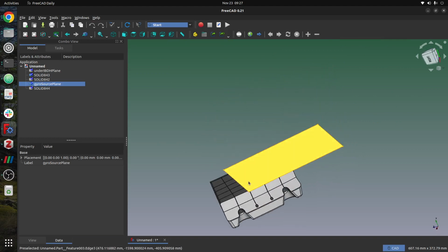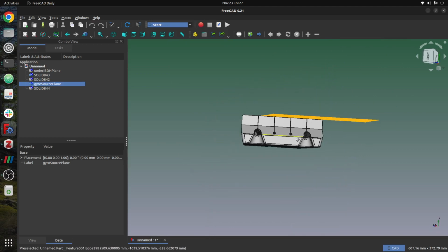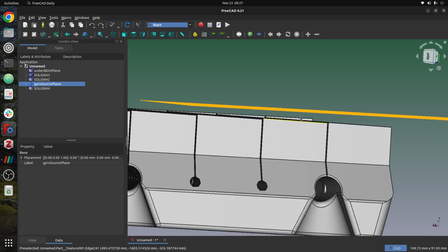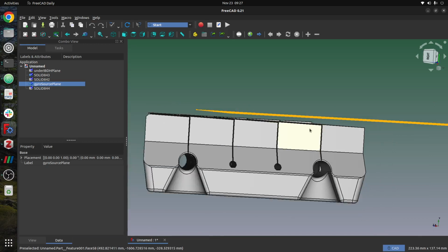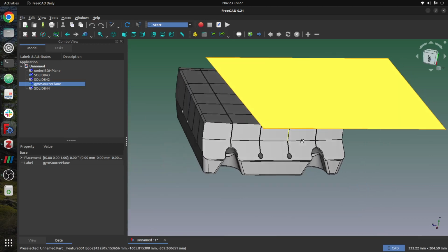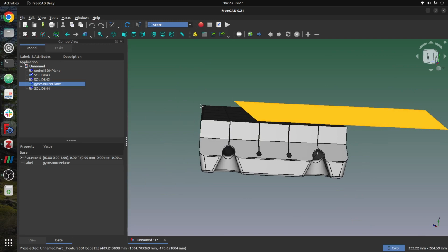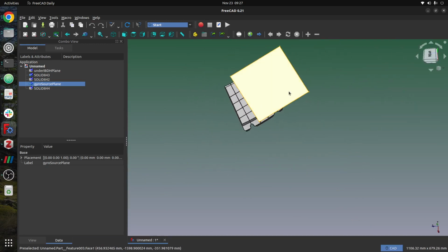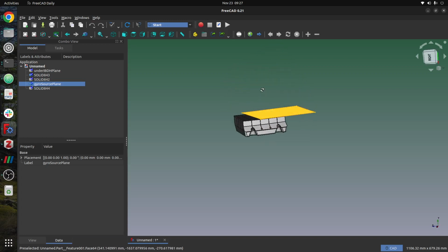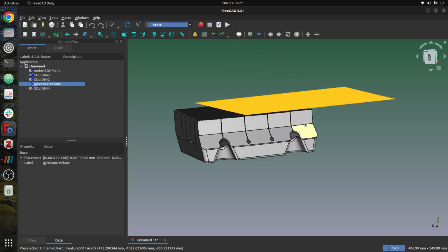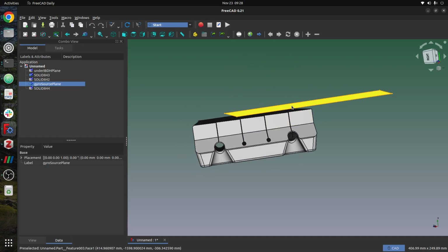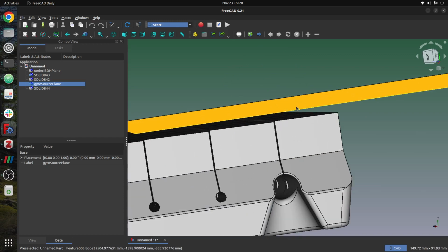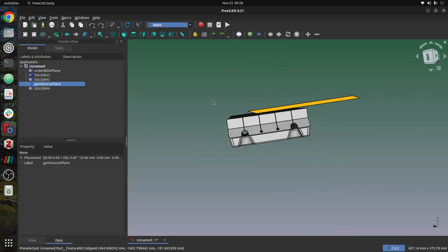Because the field lines in this particular magnetic configuration are coming from right to left and going down, I've also oriented it over here. So you can do traces from all the corners and then basically build a gyro source plane by expanding where those traces intersect. It's a little bit of black magic, like you just tune it till you figure it out. But you'll need to have a gyro source plane if you really want to accurately capture the heat flux.